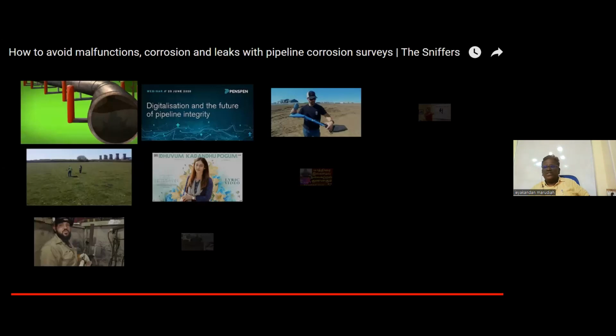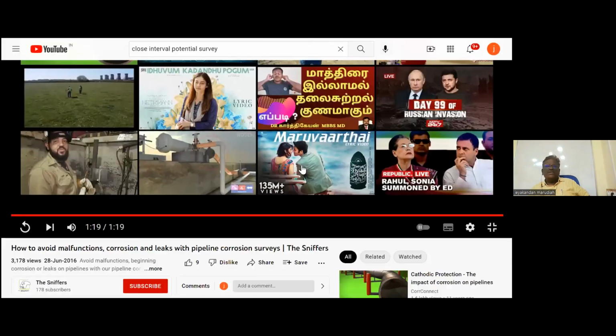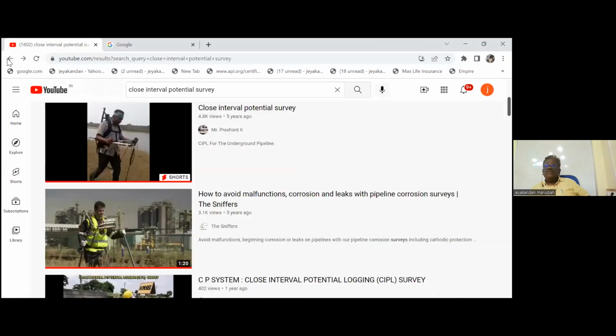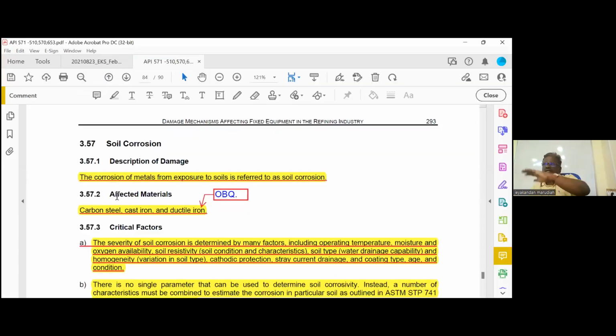See how it works actually. Not a very big deal. They will send a voltage through the electrode. See, what they are using, the stick type, it is nothing but an electrode. They will send a voltage through the soil, and when it reaches the coating, the wrapping coating is a non-conductive material. So there will be some loss. We will receive some voltage actually.